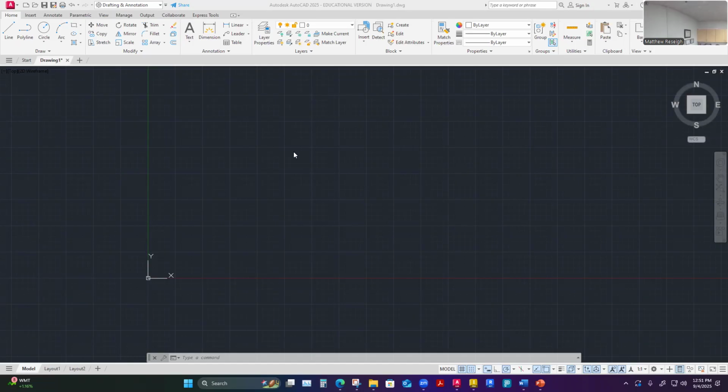Now I just want to spend a little bit of time, and towards the end of that last video, I also showed the difference between a line and a polyline. So I've covered those two commands, and they are going to be massively used. Like I said, with line you have more limited functionality, and with polyline you have a lot more functionality and the ability to join things, different shapes, and create a closed shape. There's just some strategy involved that we'll develop over how we use CAD.